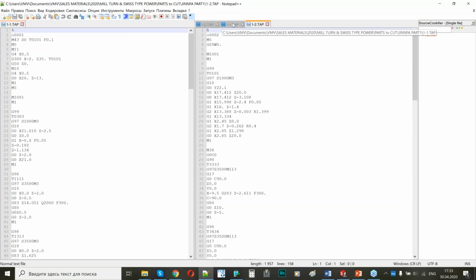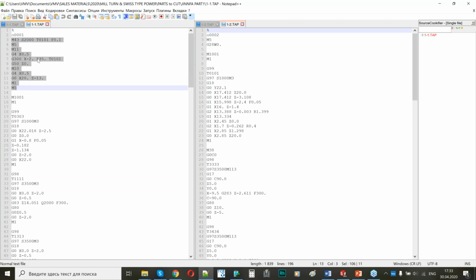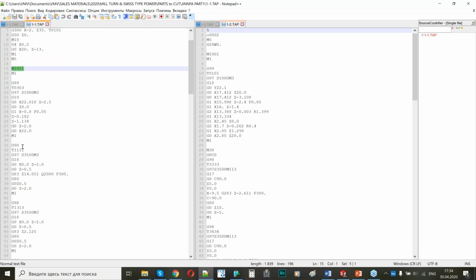So this is my G code for this machine. The GenFA machine has a FANUC controller and it has a FANUC type output, but in the very beginning you can see special codes here. It is for the main spindle movement, for clamping and unclamping, preparing the bar. Then we will have what we call wait marks for this machine. As you can see, we have these wait marks in the program for the main spindle and the program for the back spindle, and with these wait marks, the program will start together in both spindles.